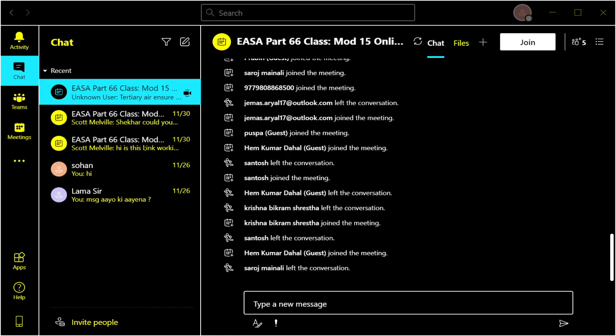Set by manufacturer, but very simple idea. What can happen through time if the oil has got some debris for whatever reason, the filter hasn't caught it, or the ball has stuck, or the spring is jammed, or whatever? Then yes, that could stay there and potentially damage the system. But usually something will blow off at some point. They're usually pretty reliable most of the time. So that's your pressure relief valve system.